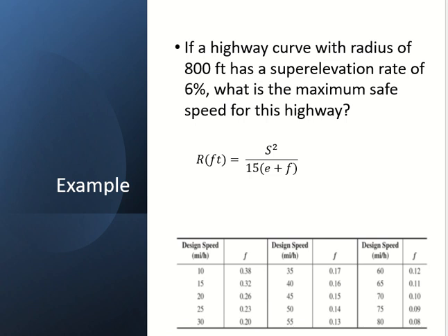No. If I go back, it will be 45, and I only tried the higher values. So I have to stop my calculation here. My final f is 0.14 and the final speed is 48.9. If there was another value which I could have tried, I would have tried that value. If my answer was, for example, 43, then I could have tried 45 because there is still a value between my answer and the assumption.